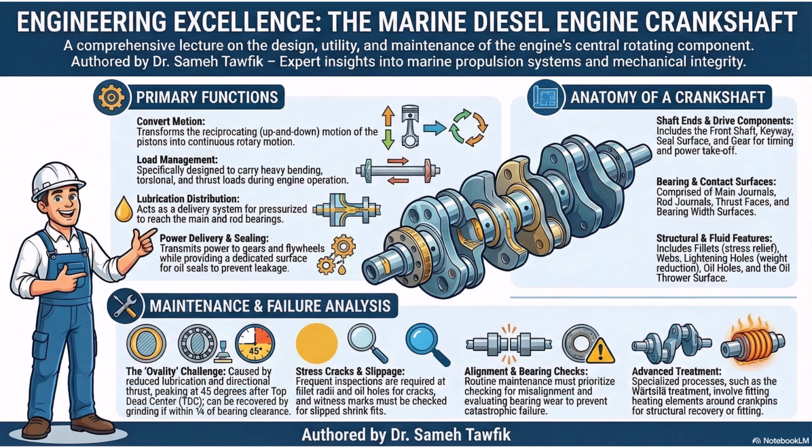And it gets incredibly precise here regarding the geometry of that thrust. The text highlights that the maximum directional thrust from the connecting rod happens somewhere around 45 degrees after TDC. Top dead center. Right. Now, since you, the listener, know engine timing, you know top dead center is the peak of the piston stroke. But why does the text pinpoint 45 degrees after that point as the moment of maximum destructive force? It's all about vector geometry and combustion pressures.